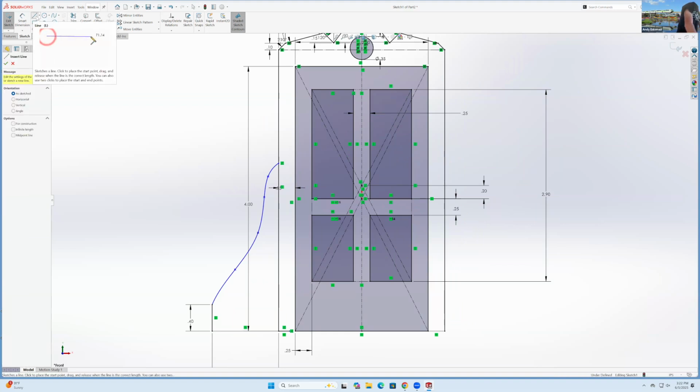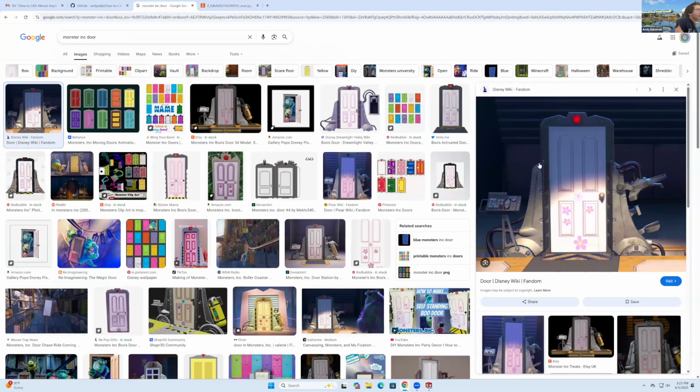Yeah, I think you could. Yes, it should be able to. Just in case, don't use a spline if you want to machine. Just use a circle, a semicircle, and that is more well defined. I think that's how I've done it in the past. That's a great question.